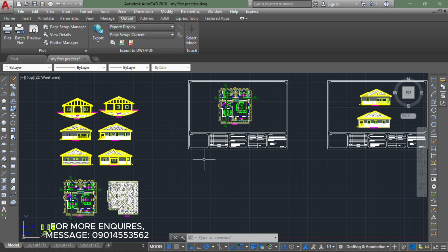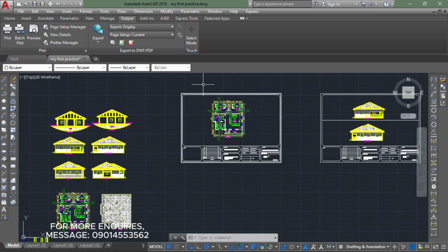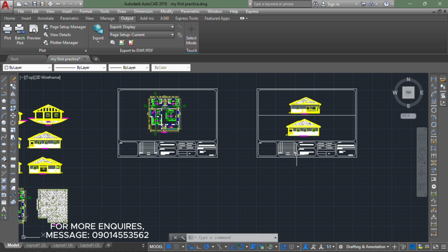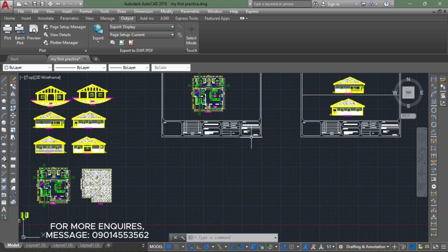For the single plotting, we have two types, right? In which you can just go ahead and plot it from your drawing. Definitely, each of your designs will be having this title block or this layout area, right? So we'll be having each of them like this. Now we can create another one, bring in our left side and the rear elevation, just like we did this. And then you have another one where you'll be having your roof plan, another one where you'll be having your two sections in it, and then plot everything singly like that, one by one.